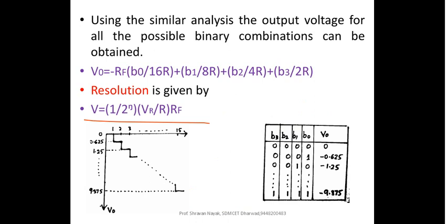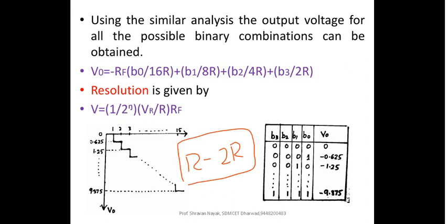So now these are the two types of digital to analog converters. One is called the binary weighted resistor type, where each bit is given a certain binary weightage, and accordingly you are going to get the analog output. Whereas in the second type you have the R-2R ladder network type, wherein only two values of resistance are required to realize the operation of the digital to analog converter.